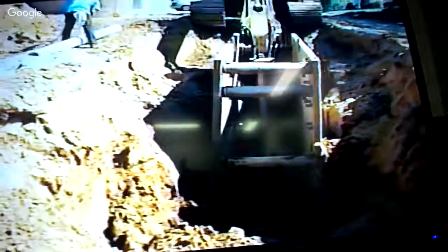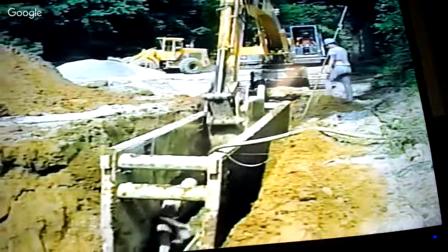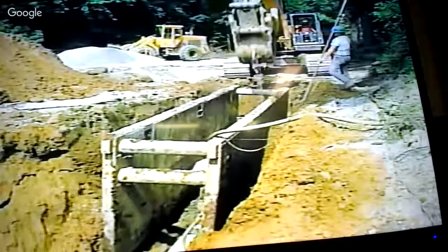Excavation is permitted below the bottom of the shield, but only to a depth of 2 feet, and only if the shield is designed to resist the forces calculated for the full depth of the trench. There must also be no indication that soil will become loose, either from behind or below the bottom of the shield.